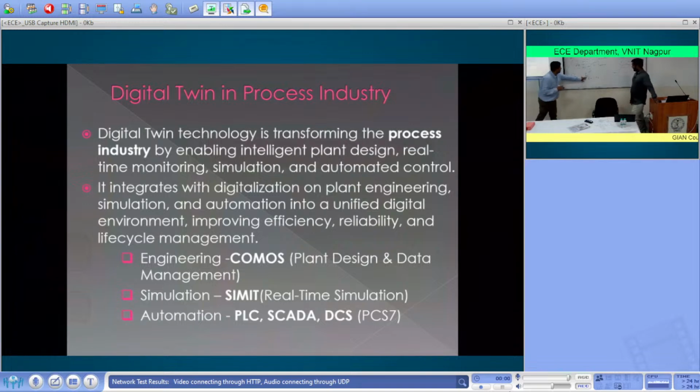Okay. We can change this to a spherical or conical area, whatever way we want. Even we can change the control valve also and check what is happening. Equal percentage control valve is there, relay control valve is there. Change the control valve and see what is happening. It will not be the same; it should not be the same.